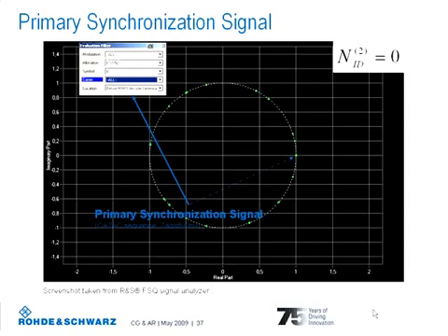By using the evaluation filter function coming with the Rohde & Schwarz FSQ signal analyzer, you can look at each subcarrier individually. For the 3 different physical layer identities, 3 different sets of Zadoff-Chu sequences have been selected, which have shown the best behavior. The one displayed in the constellation diagram is the sequence for identity number 0.